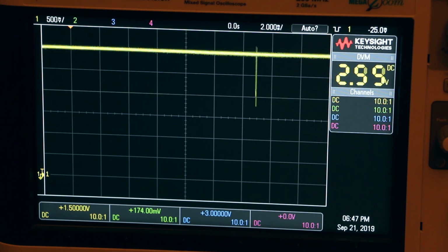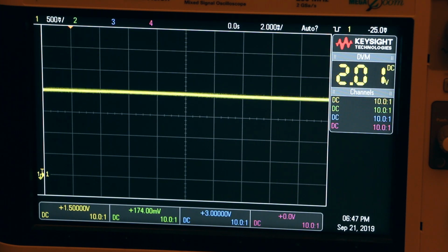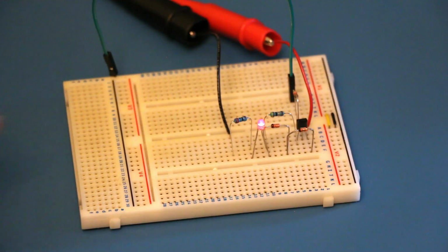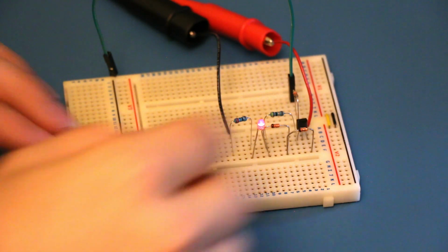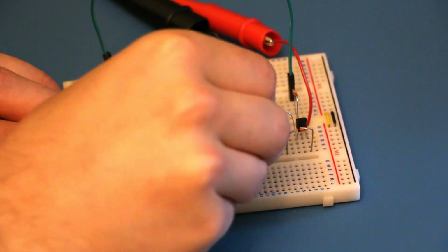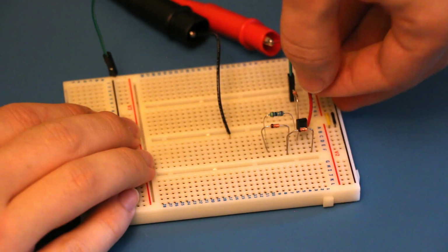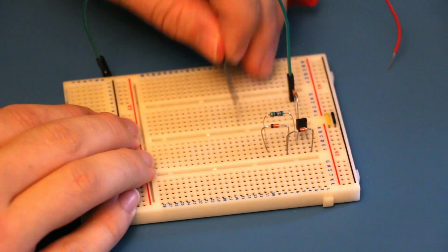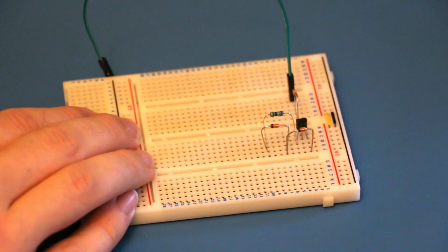Now if we pulse that in just the right way, we should be able to control the chain, and so that's what we're going to do now with the micro. Now to change this circuit slightly for the LED chain and the micro we're going to use, we need to obviously pull off the red LED and its limiting resistor, and we can get rid of the bench power supply as we're going to use the power provided by the dev board.